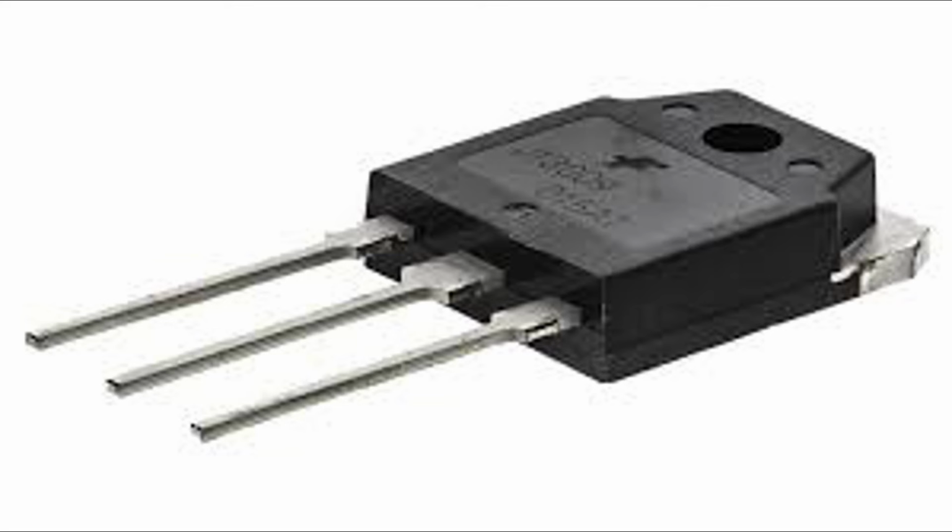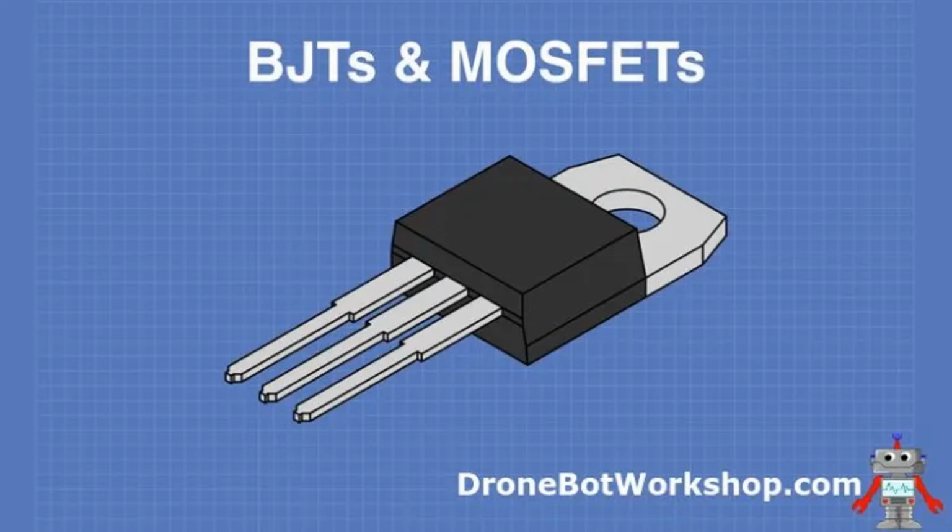Summary: the key properties of power MOSFETs (high input impedance, fast switching speed, low on-resistance, thermal stability, high voltage and current ratings, the presence of a body diode, gate charge characteristics, and the Miller effect) make them versatile and essential components in modern power electronics. These characteristics enable their widespread use in various applications, including power supplies, motor drives, automotive electronics, and renewable energy systems.